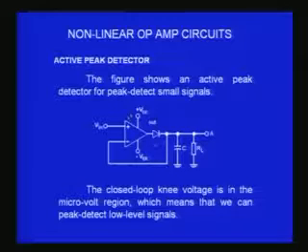You can see on the screen now I have shown the circuit of an active peak detector using a precision diode here. The diode on the op amp is in the form of an ideal diode by having it in the feedback network, and the output I connected to a capacitor along with the RL. So if the time constant of the RLC is very large, then you would find the input signal will charge the capacitor to the peak value, and before it discharges the next peak voltage will come, etc., and therefore it will almost remain at the peak voltage except for the small loss due to the RC time constant.